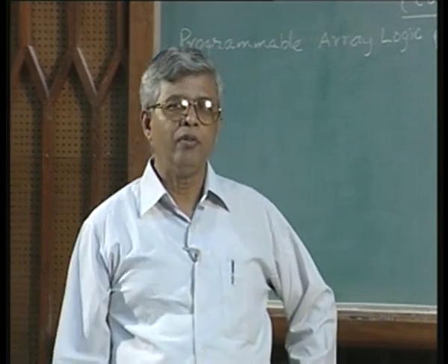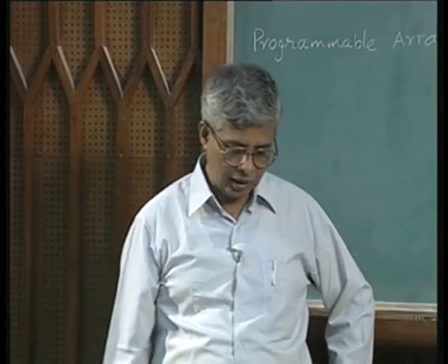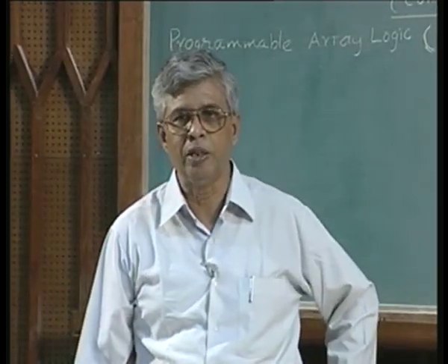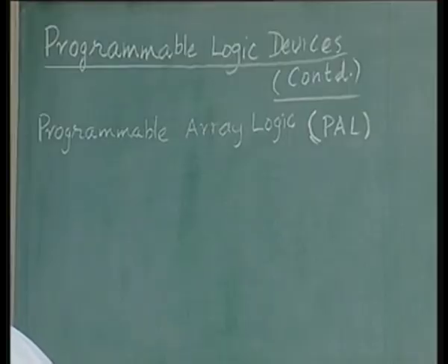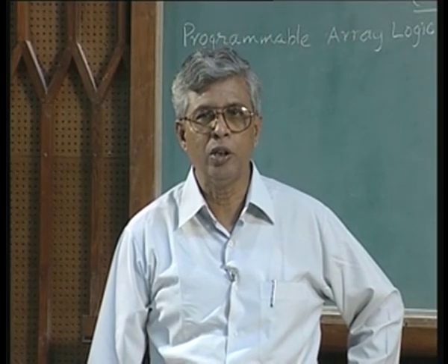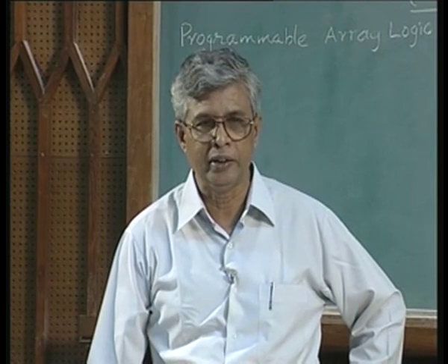The same concept of reducing the function to get a few product terms rather than all the minterms will be followed here. That means the approach is similar. So, we will program the input variables into a few product terms which are required for implementing the functions.